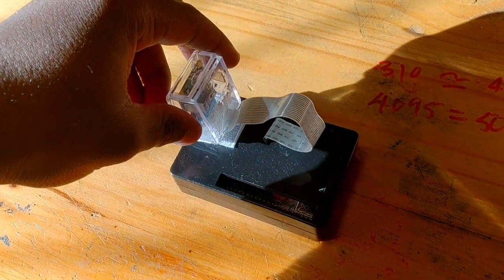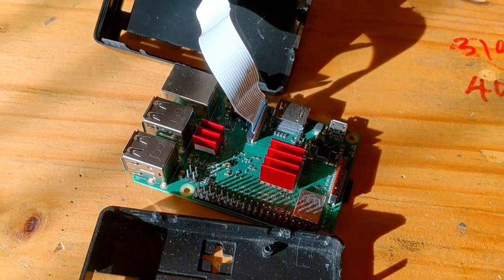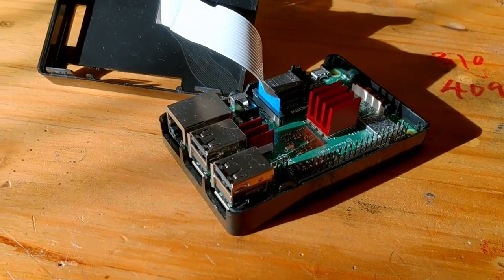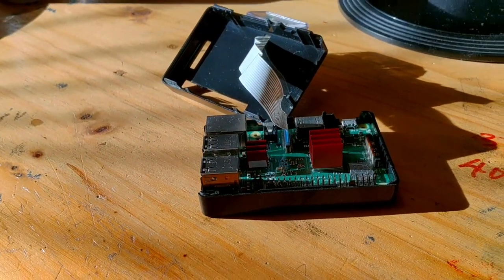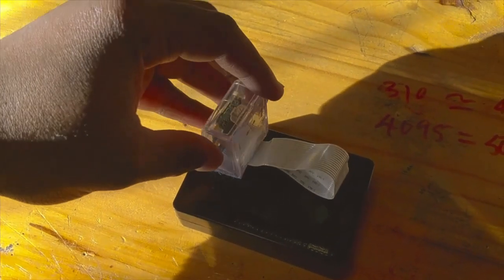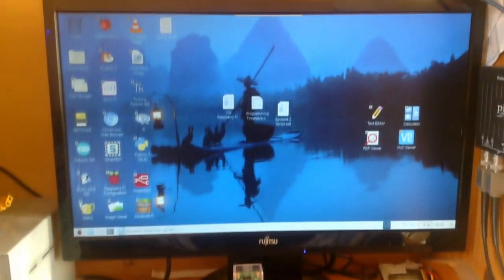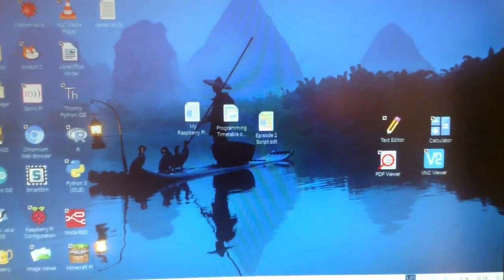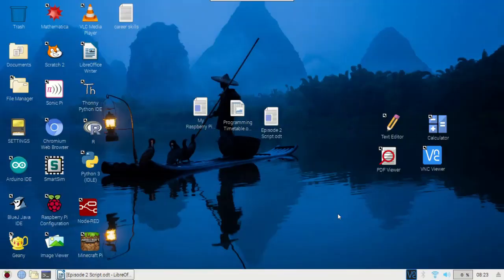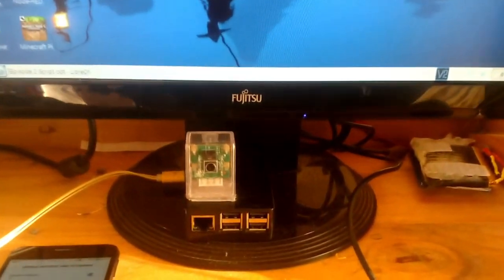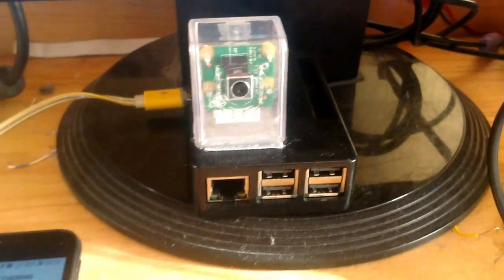The Raspberry Pi's GPIO pins can only supply up to 50 milliamps, so it's advisable that any device that requires more than 50 milliamps from the GPIOs be supplied with an external power supply. The HDMI port uses 50 milliamps. The keyboards and mice can take as little as 100 milliamps or over 1000 milliamps. But since I use my Pi over a VNC server, I don't need to worry about these power demands. Check the power rating of the devices you plan to connect to the Pi and purchase a power supply accordingly.